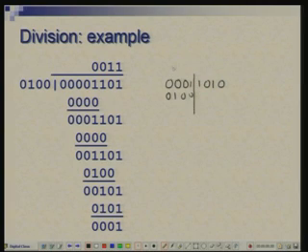So, this is RH and this is RL, and I will always be working with D, which is n bits, and RH, which also is n bits. Okay. So, they will be compared and subtraction will be carried out. So, the next time R will be shifted left, D will remain here. Okay. Instead of shifting D, we are shifting R left. So, the starting position is here, which must be carefully noted.